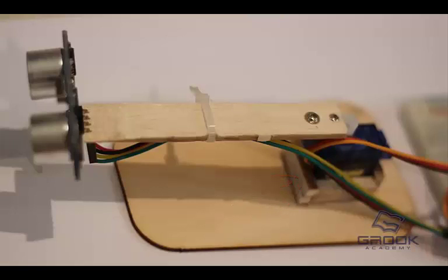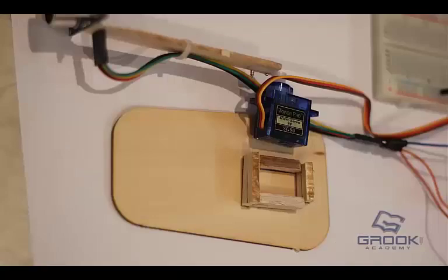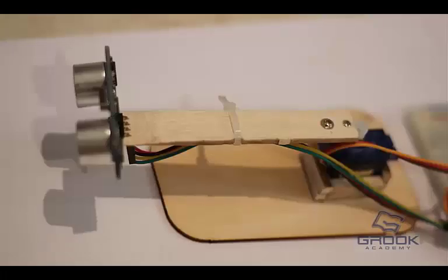You can use any suitable servo. In this project, we have used Tower Pro Micro Servo 9G. It can rotate from 0 to 180. In this project, we have used from 45 to 135 degrees. We used some balsa wood for making the base. We tried to keep it very simple. And of course, wires and breadboard.